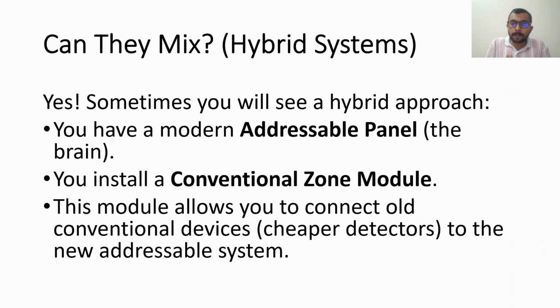There are some guidelines which say that in this particular room you need to use explosion-proof devices. So in certain brands, the explosion-proof devices may be conventional devices. The conventional devices you cannot connect directly to the addressable system.